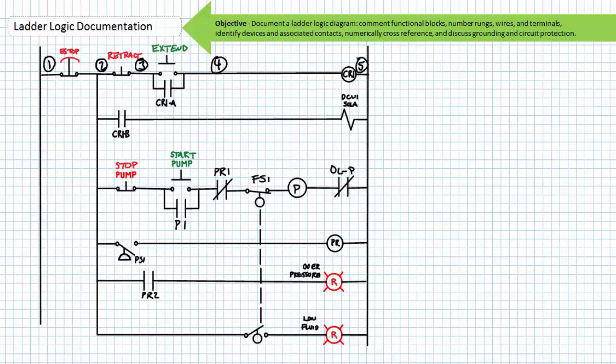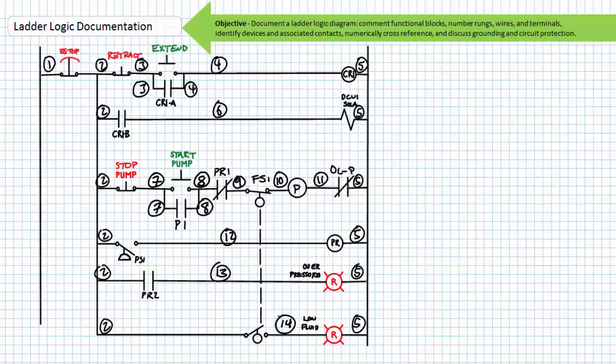Once the right vertical upright is reached, all devices attached to this common connection are assigned this number. In this case, the wire number is 5. Method 2 then continues as did method 1, assigning wire numbers left to right, top to bottom. Notice we still top out at 14 wire numbers, only wire 5 is now the right vertical upright instead of wire number 2. I know, this method drives me crazy too.